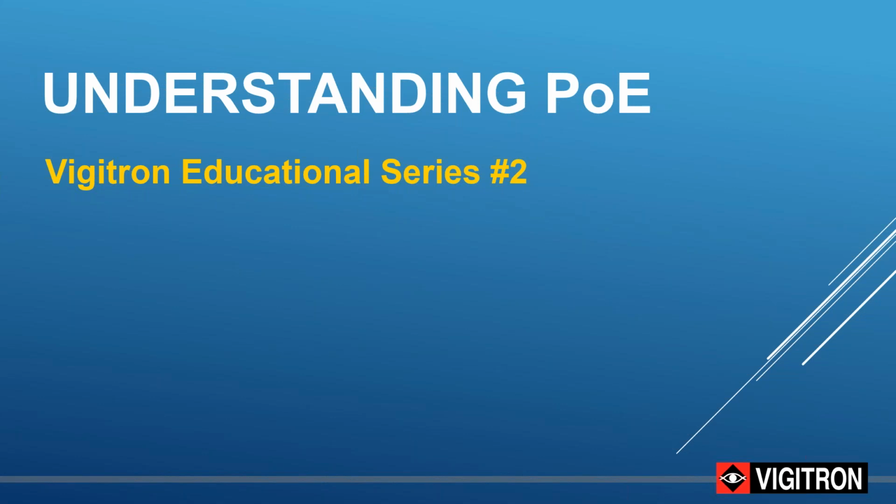In seminar number 2, we're going to be focusing on Power over Ethernet, or PoE. This is perhaps the most misunderstood component of networking due to all the variations involved. Often we think about the IEEE standards, such as those applied to 802.3af or at, as fixed values. They are anything but. The process of determining how much PoE is required is made more complex by all the variations within the operations and the growing requirements for more power over what is consumed within this standard.